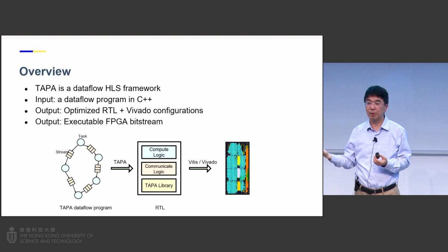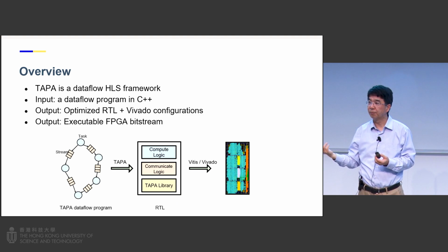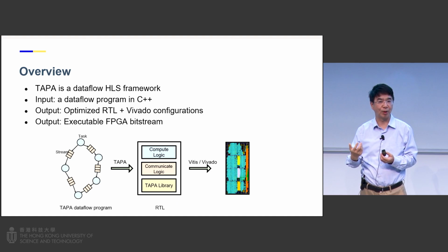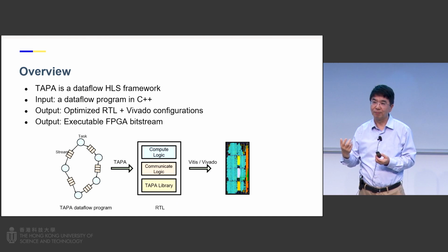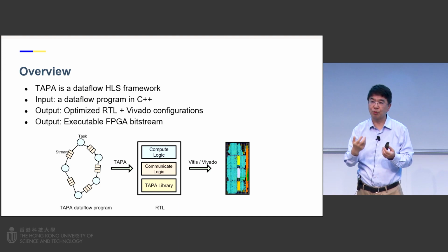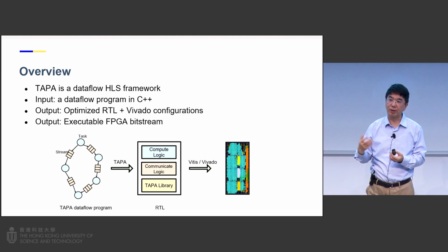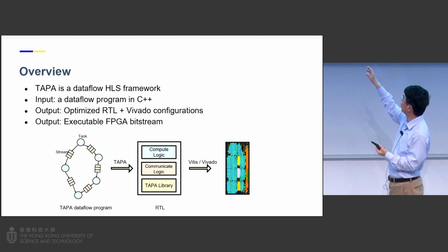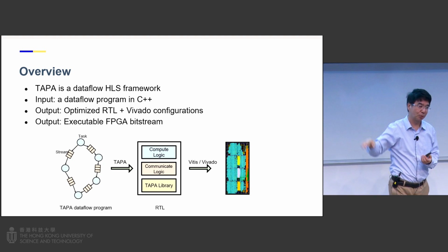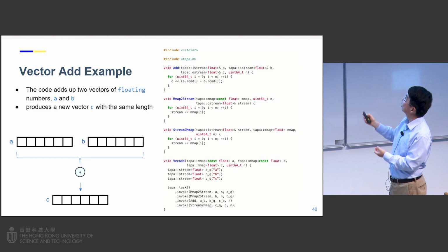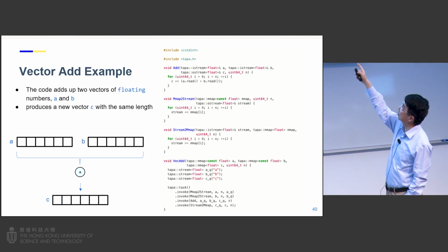What are other possibilities? How otherwise can you communicate between different modules? Yeah, you can communicate through shared memory, for example, or some double buffering. There are other ways, but we just want to standardize. You want to make FIFOs the communication, and then the code you can see is actually very simple.